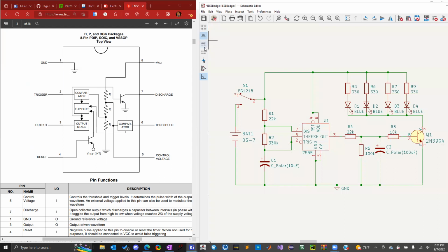You have inches and millimeters, but then you have this unit called mils. Mils is not a millimeter. Mils is 1/1000th of an inch, and it's just a more accurate distance measure, because sometimes in PCB design things are so small you want them as close as possible, to the 1/1000th of an inch, to each other.